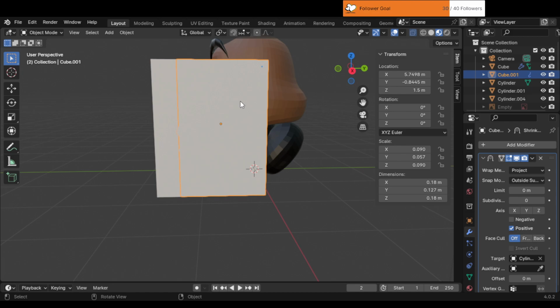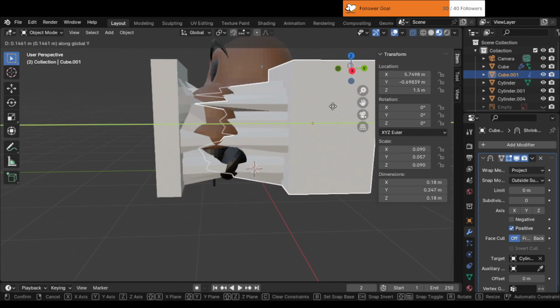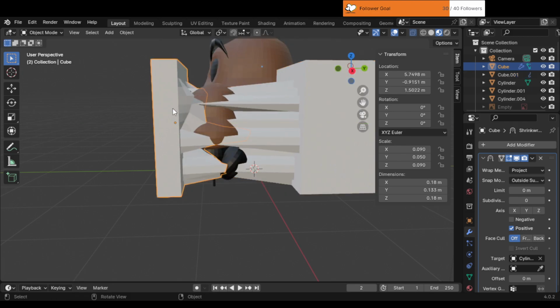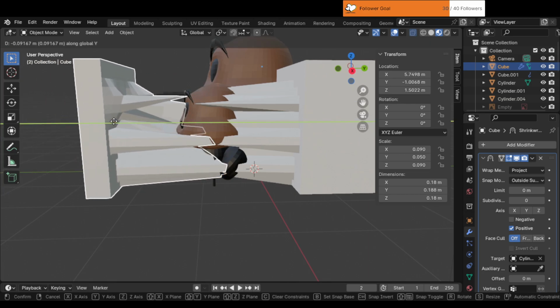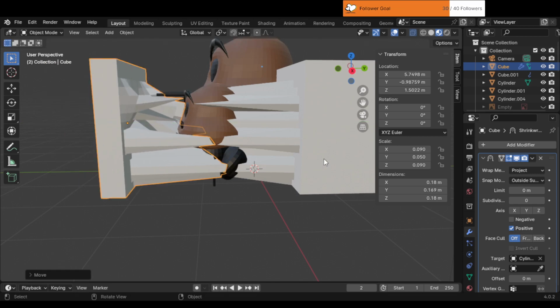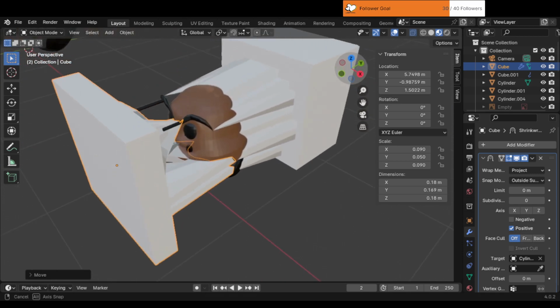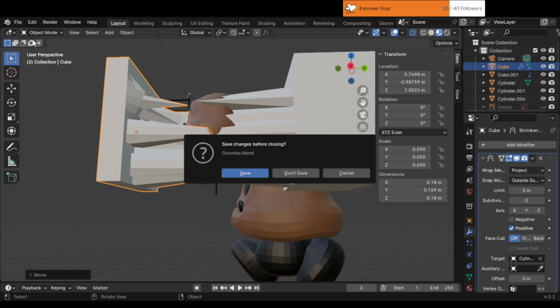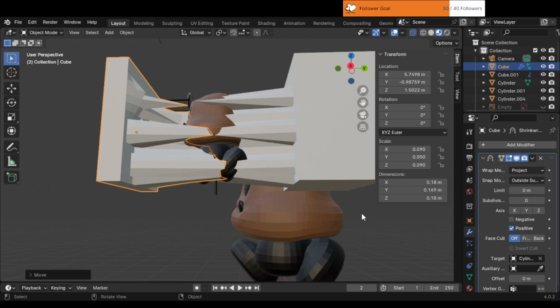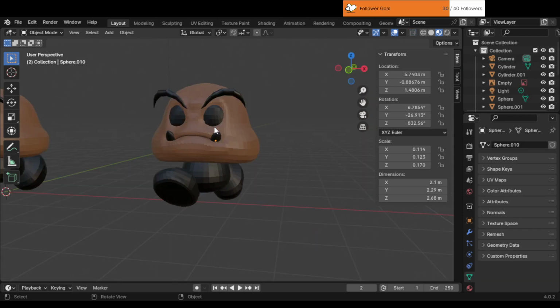Potential issues. 1. Complex geometry. If your model is composed of joined items with complex geometry, it can complicate Boolean operations or shrink wrap effects, possibly leading to unexpected or undesirable results. 2. Non-manifold meshes. Joined items may create non-manifold geometry, such as faces intersecting or overlapping, which can interfere with Boolean operations and shrink wrap effects. 3. Multiple meshes in the model. If your joined items consist of multiple separate meshes, the operations may struggle to process them properly.